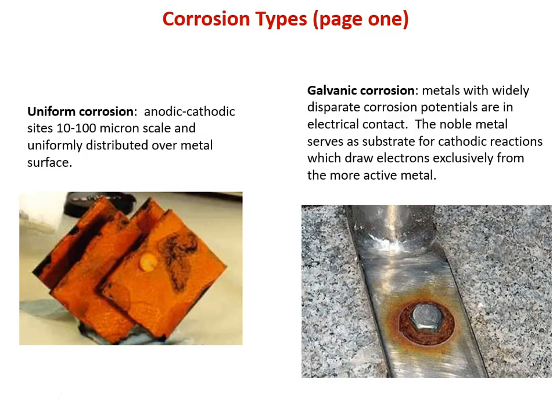A little bit less nice and less easy to predict is galvanic corrosion, and here's one of our first instances of big cathode, little anode. As you can see, we have a washer that's probably a plain carbon steel or maybe high strength steel, underneath the bolt head. It's being bolted to something that looks an awful lot like stainless or nickel alloy, which is acting like a gigantic cathode and is actually probably reducing oxygen from the environment, given that it doesn't look like it's in an acidic solution.